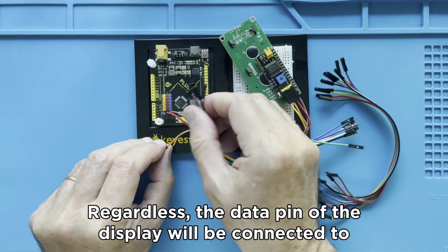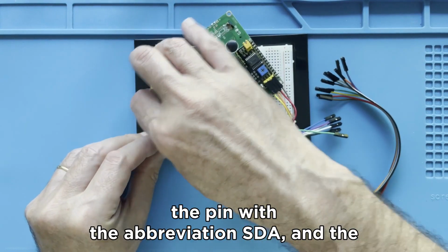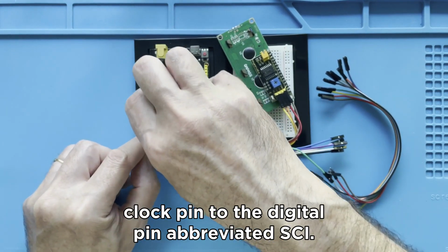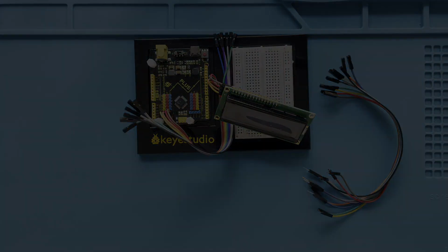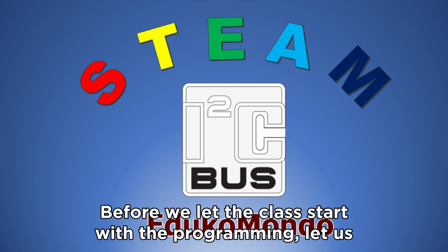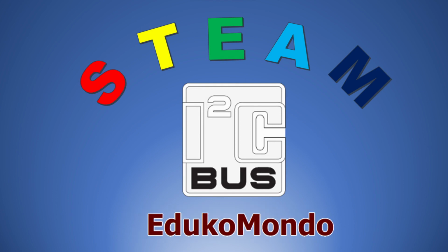Regardless, the data pin of the display will be connected to the pin with the abbreviation SDA and the clock pin to the digital pin abbreviated SCL. That's it for building the project on the breadboard. Before we let the class start with the programming, let us explain the origin and advantages of the I2C protocol.